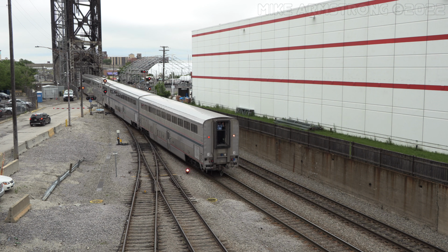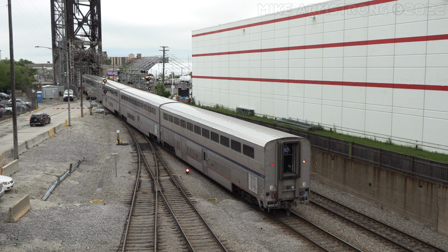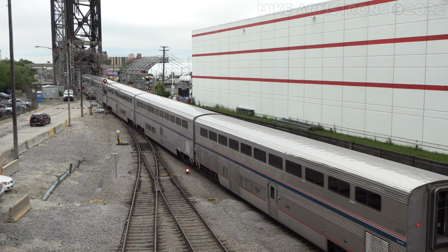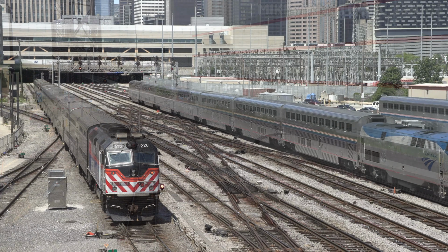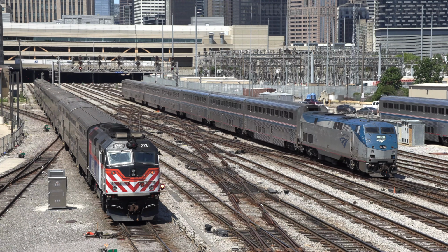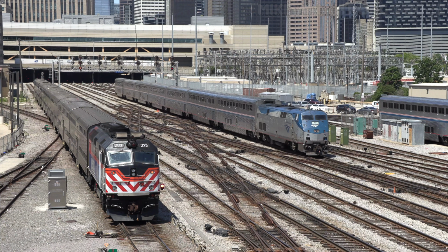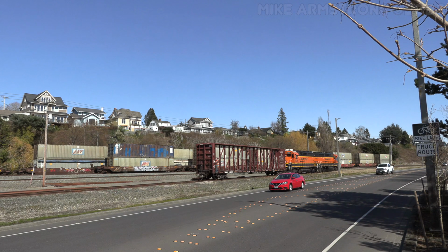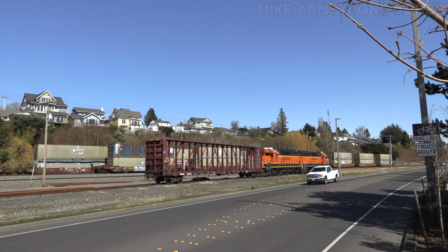In order to do this, a crew member, most likely the train conductor, would need to be positioned at the end of the train to communicate instructions to the engineer and make sure the line is clear. Moving a train in reverse without crew protection is what's called a blind shove, which is against federal regulation.